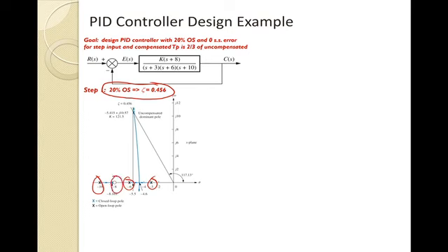Now what we can do is vary our gain K such that we're on that damping line as desired. And when we do that, our uncompensated dominant pole for a value K of 121.5 is going to be there. And then you can see how the other poles will migrate relative to that.